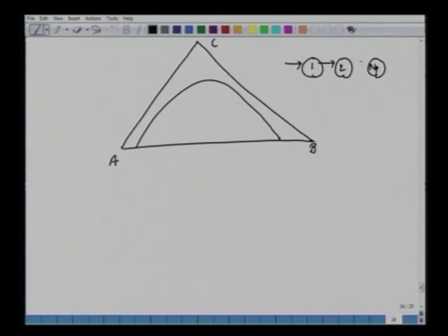So we have feed getting in like this, let's put a break here, and then we have treated feed, and we have counter current. This is solvent S, this would be RNP, nomenclature NP stands for the stage from where this raffinate phase originates. So this should be extract ENP, right? So this should be E1, this is F, so this should be R1, then R2, etc. So this is E2 again, and similar corresponding weight fractions.